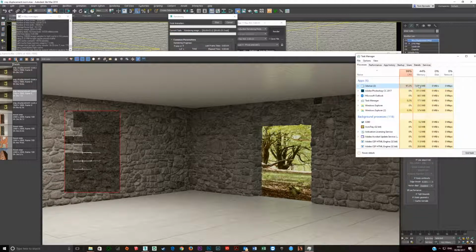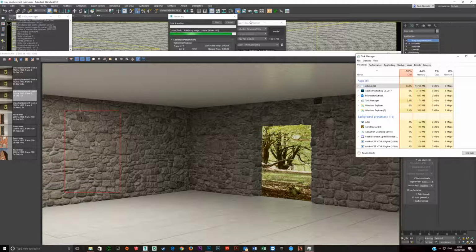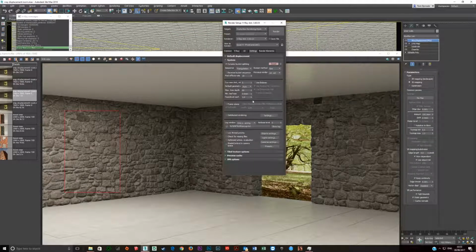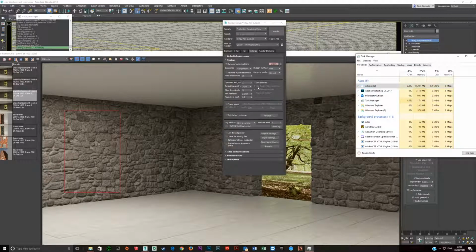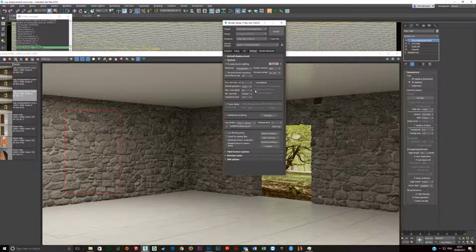That's, what, 6 or 7 gig of memory less than it was using before. So yes, Embree uses a lot of memory. It can speed things up. It does usually speed things up. But if you turn it off, you can save a lot of memory and a lot of resources. If you don't need to turn it off, leave it on and click Conserve Memory.